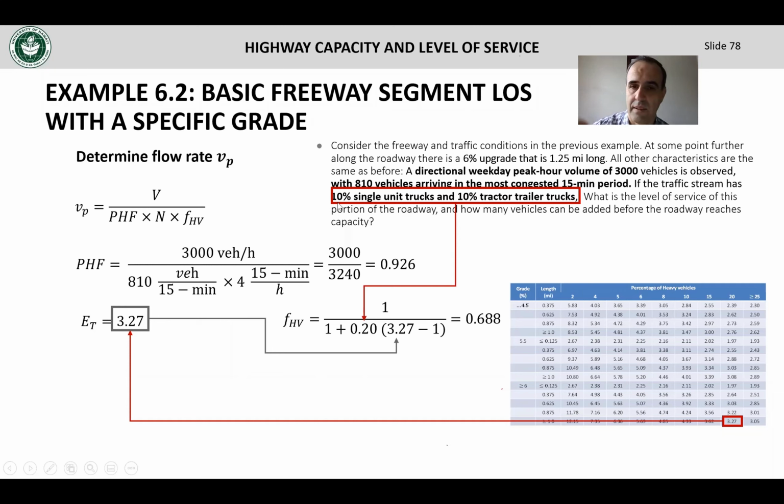But now, and I look at the notes a little bit earlier, I should have put an arrow pointing to this table with this information, because this information I'm also using to select which table I'm going to use. If you go back into your textbook, table 6.5, I think 6.5 is used for, well, I don't remember if it's 6.5, 6.6, 6.7, or 6.6, 6.7, 6.8, but the one in the middle corresponds to 50% single unit trucks and 50% tractor trailer trucks. So I pick the table corresponding to 50-50 because these 2 numbers are the same. Is that clear?